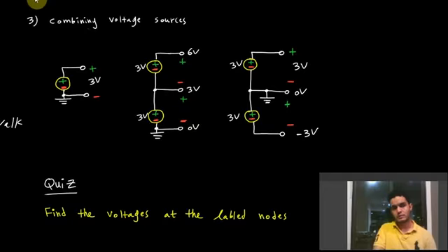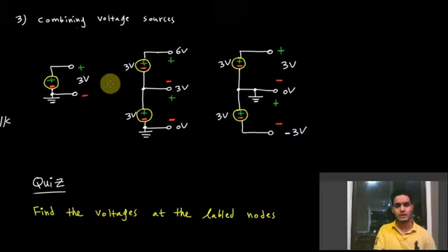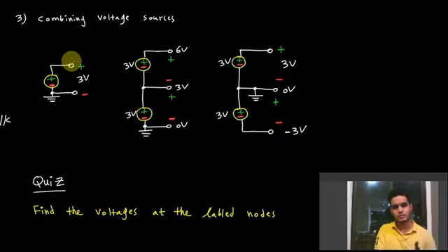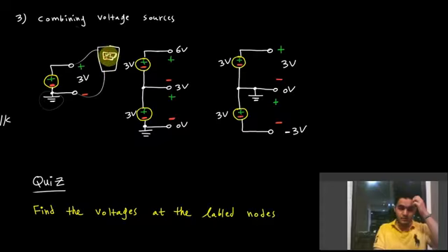So that's another practical application there. Say you have a voltage source here with the positive and negative terminals defined as such. It is 3 volts, and the ground is here. You've grounded at the negative terminal, as is common. So if you put the probes here for your multimeter, for example, you're going to read what? Plus 3 volts. Now that looks like a 2, that should be a 3 volts. Now if you look at here, you have 2 voltage sources combined of the same voltage.